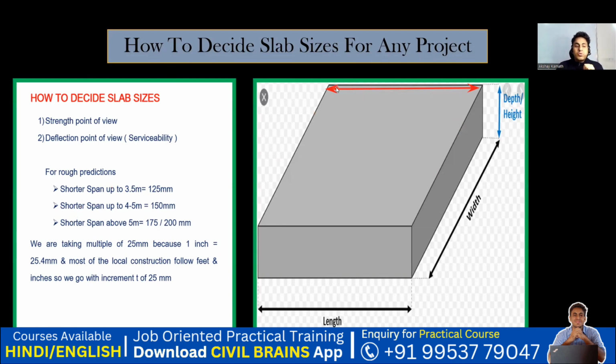If your shorter span is 4 to 5 meter, you can go with the thickness of your slab as 150 mm. And if your shorter span is greater than 5 meter, you can go between 175 to 200 mm. That means either you can take 175 or 200 mm depending on the load coming on that. But these are the minimum sizes you're supposed to do. We can make use of this slab thickness so that we can design any project. Anyhow, we'll take that as an example and try to see that.